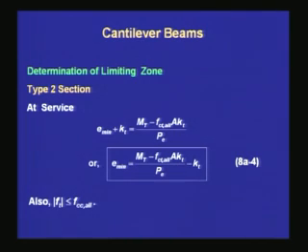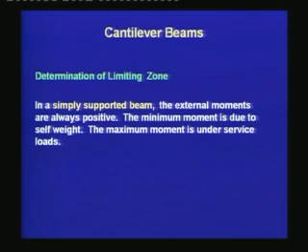Also, we need to check that the stress at the top should be less than the allowable compressive stress under service conditions. With this recapitulation of the determination of the limiting zone for a simply supported beam, we are moving on to the determination of the limiting zone for a cantilever beam.